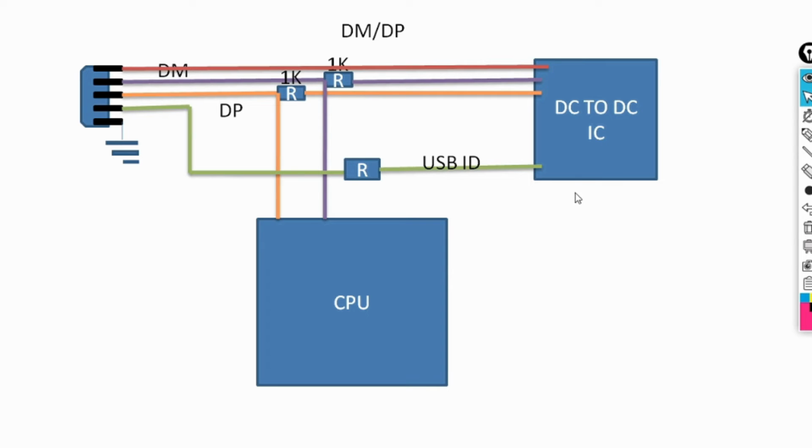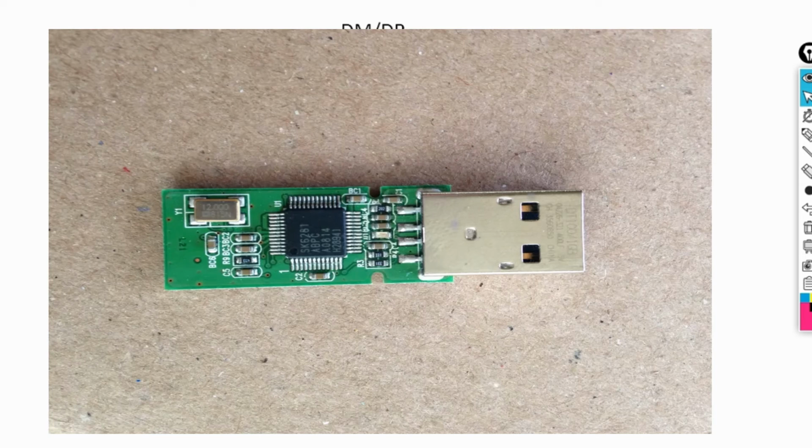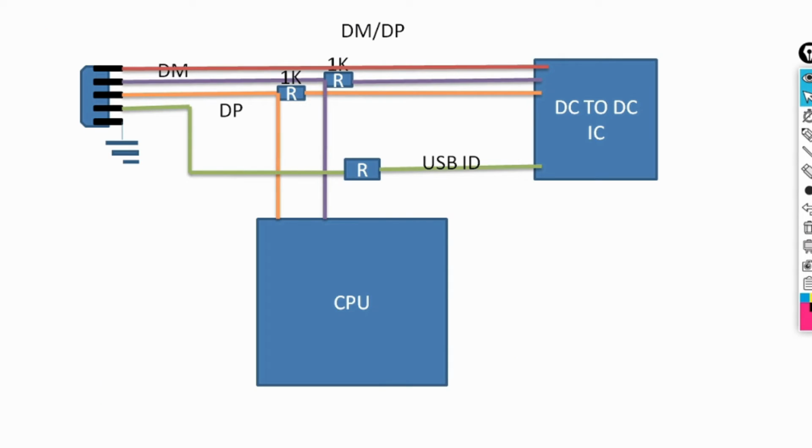When you connect the OTG, your flash drive or pen drive, your USB card reader has 4 points. You can open it and check it. Positive and negative, the first one and the last one, are to run the OTG or your flash drive, right? In between, the two, DM and DP, are for data transfer, right?